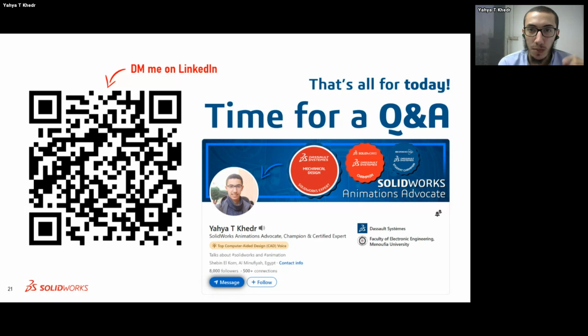But instead of going one by one and configuring each feature, you can create a table with the length, the width, the diameter of the hole, the width of the hole, and the position of the hole in X, Y, and Z directions. Then all you have to do is enter the values. Configuration 1, here are the values. Configuration 2, here are the values. All of these values will be saved in this design table, which is much easier for you to manage and control all of your configurations. There are many different ways to approach design tables inside of SOLIDWORKS.